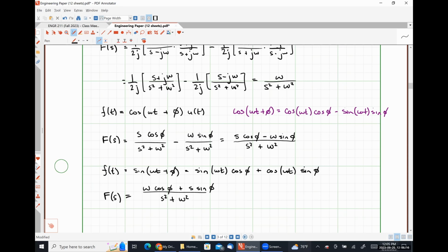I mean, they do the relationships, but as far as a problem goes, it's the exact same thing as we did. If I gave you something with a three-phase transformer, which I'm not, it would be for a balanced load, which means you could look at it from a single-phase perspective, and it's exactly the same thing that you've been doing. So I'm not going to give you anything with unbalanced loads because then none of the three-phase relationships work. So what's the point? Doing single phase is just the same as doing three-phase. Everything's just shifted by 120 degrees.